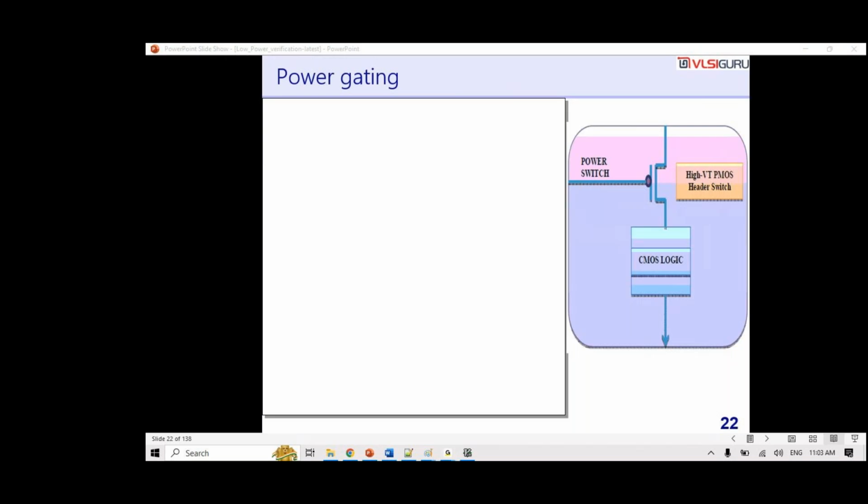This control, tell me who controls it. Is it controlled by this voltage or this voltage? Let's say A, B. Is it basically the switch on or off? Do we control it by the drain voltage or the gate voltage? Gate voltage, right? Because whether the transistor should be in the cutoff region or in the saturated region will be controlled by the gate voltage.